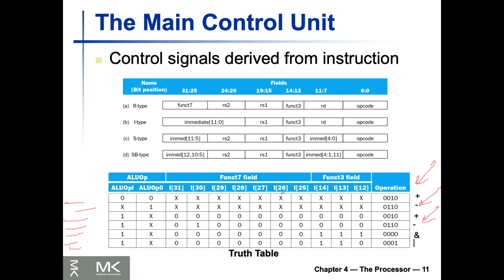For many of the instances, the same goes with the truth table. We don't care. So those crosses are the don't care state because they were not actually needed under the specific line. Okay. The inputs that we have in the truth table are ALU op and func field, right? So the func field and ALU op are the input. And so here we are seeing a subset of that.